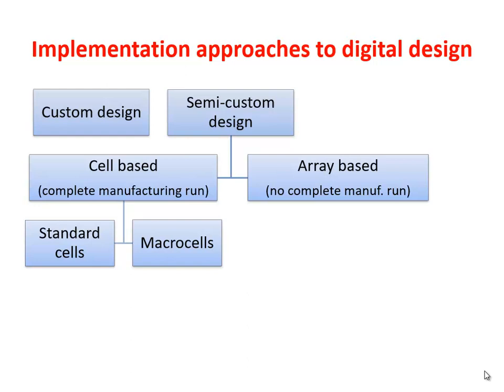The front end is all the processing up to the complete fabrication of the transistors, and only the interconnections have to be put on top. So the chip is designed except for the interconnections, and you need to design and to fabricate only the interconnections between the different parts. This type of array-based design is called gate array.